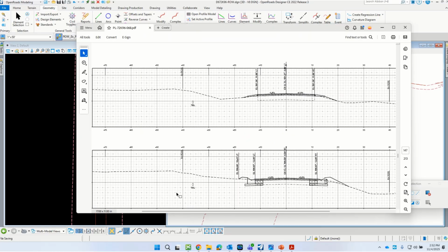Okay. So when we talk about that right-of-way cell, I just brought up the cross-section sheets, instead of just talking about it, to show you what I'm talking about here. So, ultimately we're working towards generating the model and generating cross-sections from that model. Well, these cross-section sheets are annotated. And so see this existing right-of-way line here? That's actually a cell.